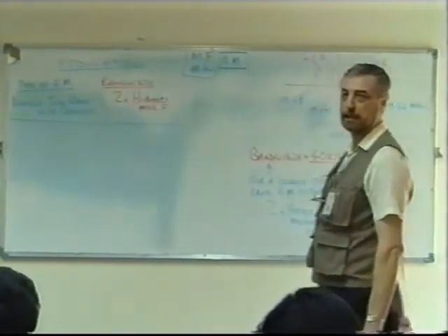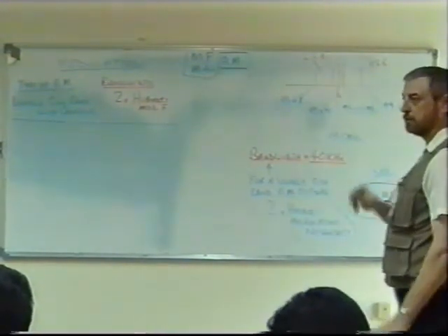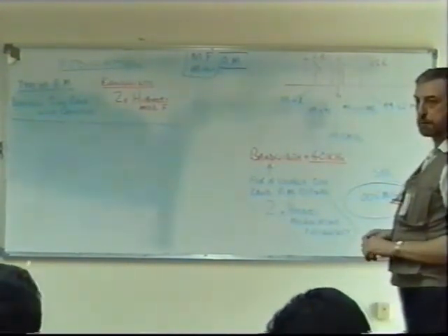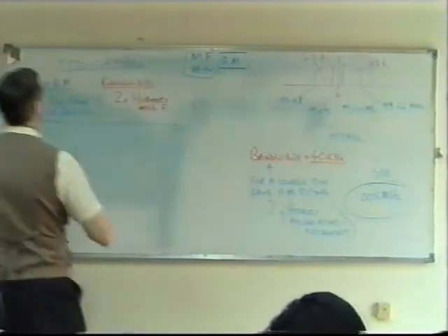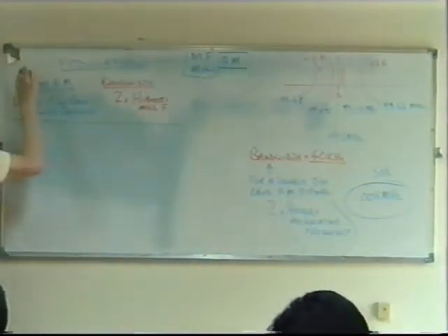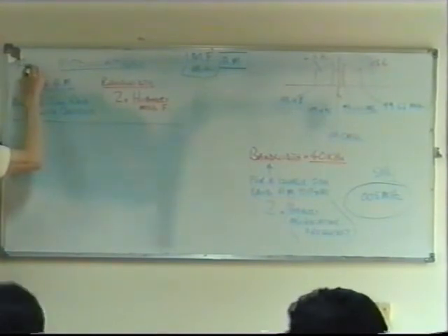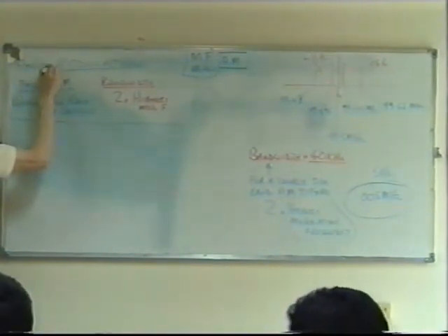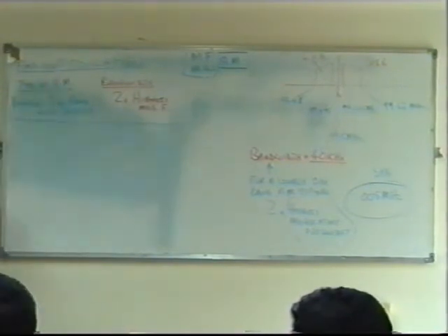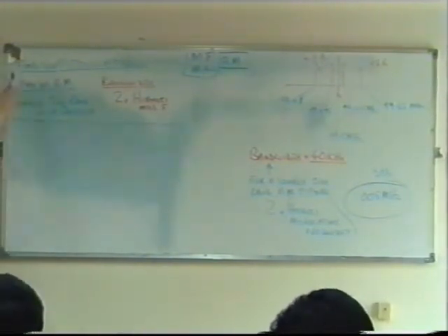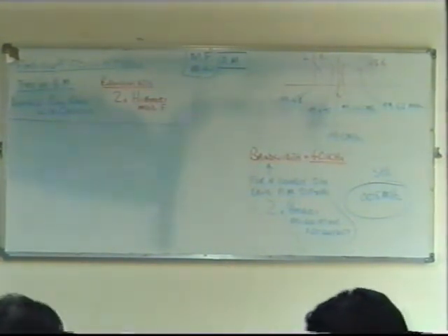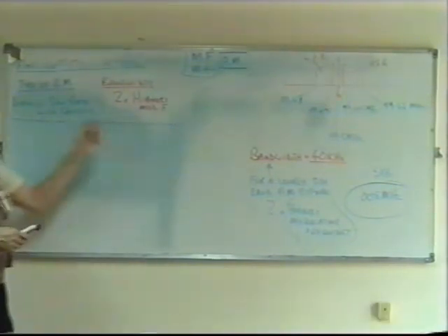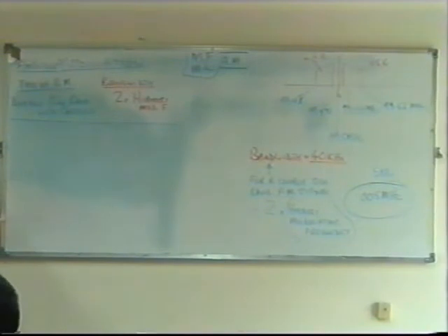Now I'm going to describe a slightly different variation on AM, slightly different types of AM. Amplitude modulation, AM. In fact, let me just head this whole thing and call it amplitude modulation. Amplitude modulation is the type of modulation we're talking about here in all these examples. Double sideband with carrier: the bandwidth is 2 times the highest modulating frequency.